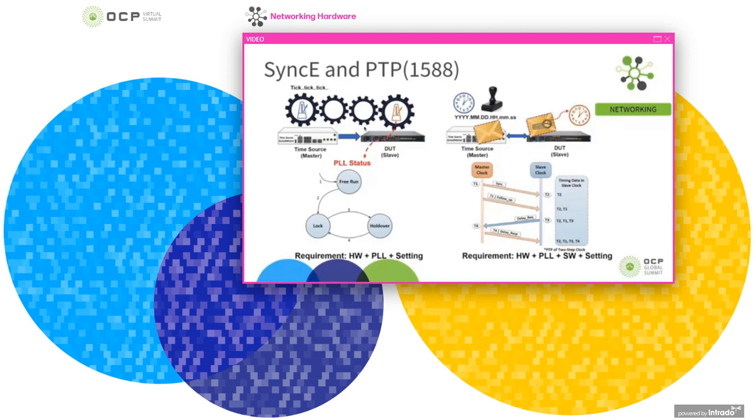1588 is a little more complex than SyncE because it needs hardware support, what we call a DCO, digital controlled oscillator, in order to let the software fine-tune little by little to achieve time sync. So you need hardware skill to implement the overall system, especially in the integration.